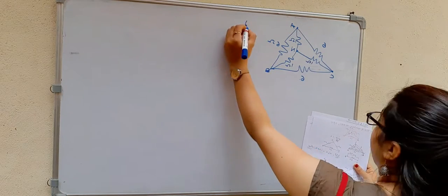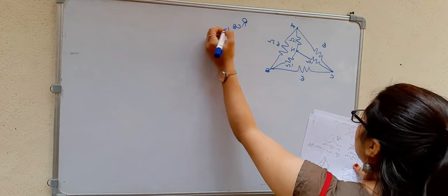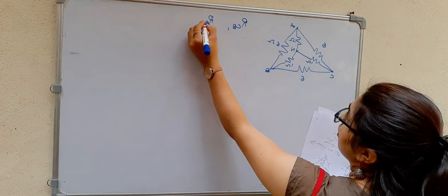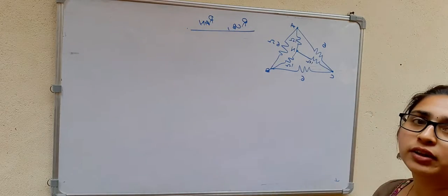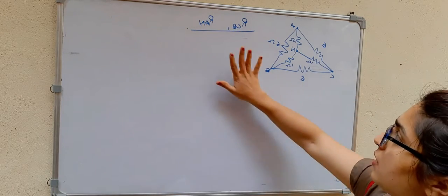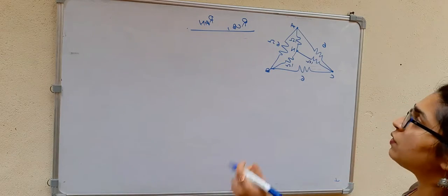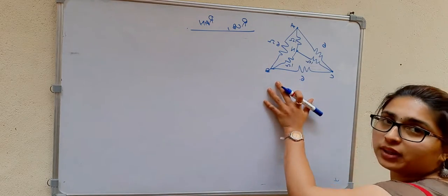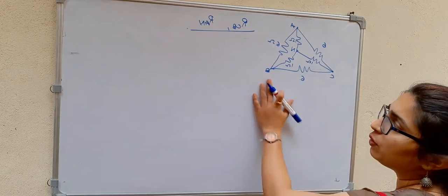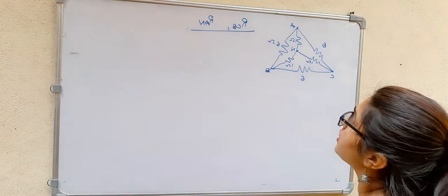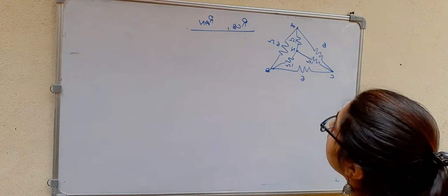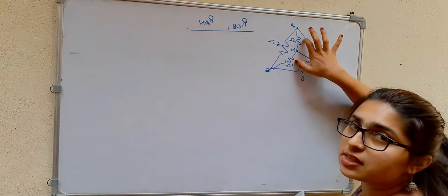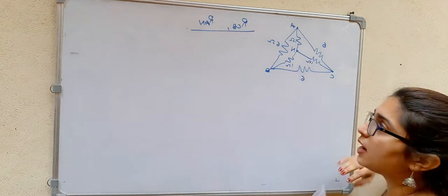Here we have to find RCB, then we have to find RAN. So we have to find the two equivalent resistors in this case. First we will find RCB, that is between these two terminals B and C, the equivalent resistance. What I can do in that case is convert this star which is inside the delta to star.